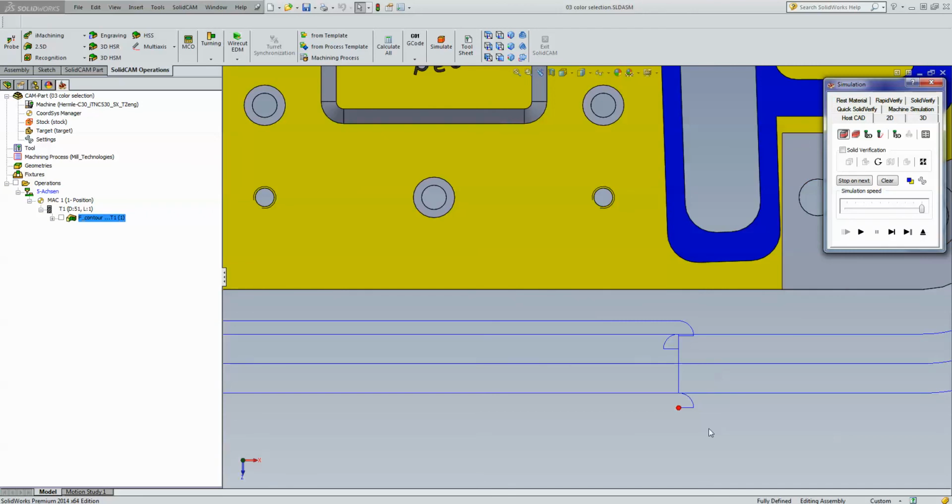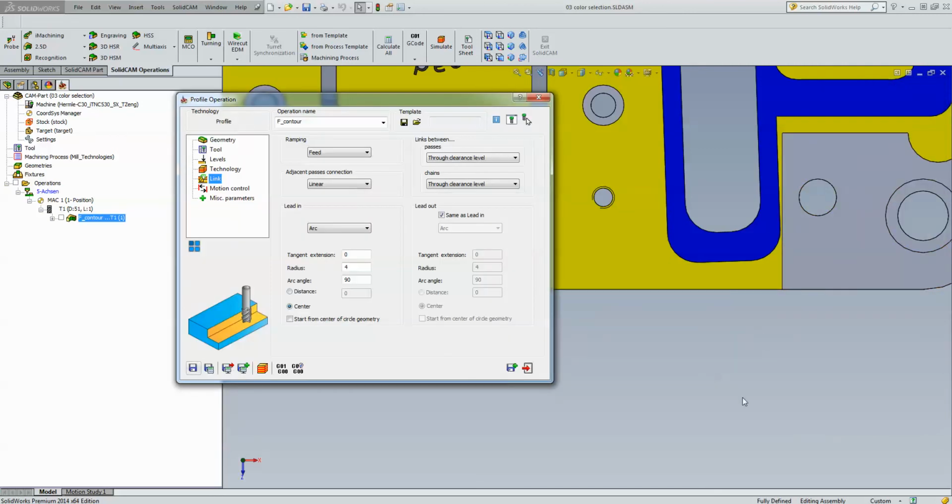Okay, but in many cases, and many people, and myself also as well, I do not like to go directly into material. So what we've added over here now for the clear offset option is as follows. We have now adjacent passes connection. By adjacent passes connection, we just had adjacent passes over here. How do you connect between them? We had a default of linear, which is the way I showed it to you right now. But we also have two more options. One is rounded, where it rounds out of one and then goes straight to the next one, but then rounds into the next one as well.